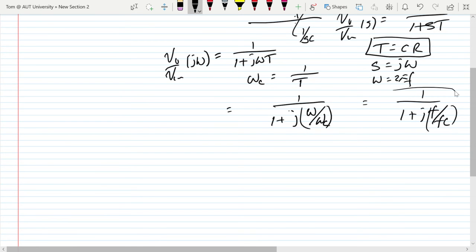This is preferred by many electrical engineers. The s domain is control systems people, and some people use omega as well. And if you remind yourselves of what the Bode plot looks like, when f is equal to 0 here, there's no gain in the system. Well, there's a gain, it's unity gain. When f is 0, that disappears. And 20 log of the base 1 is 0, so it's 0 dB of gain